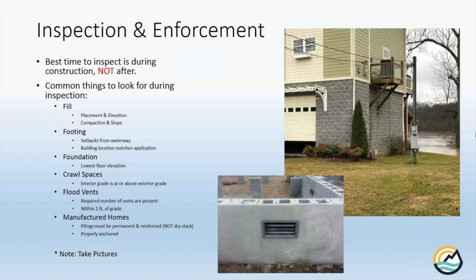Whereas if you come out and look at it after they've got the foundation in, you can really easily say, hey, that's not high enough. You need another row of bricks to make sure you're up above that flood elevation. That's much easier than doing it after the fact. Some of the common things we look for whenever we're doing inspections are going to be looking at fill. Is it placed where they told us it was going to be? Is it as high as they said it was going to be? Are they compacting it? Things like that.